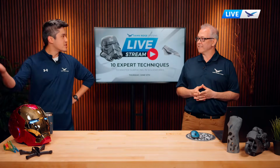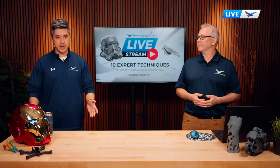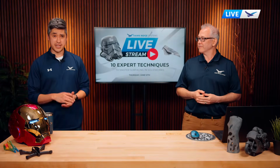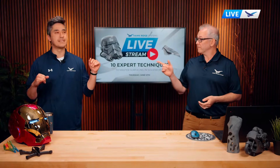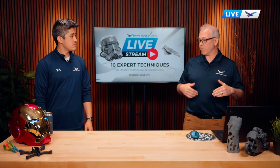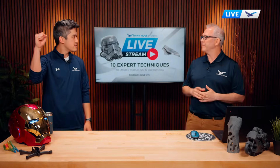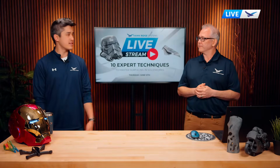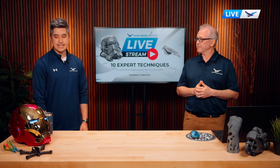I was saying, how many features are in this model? How would we even go about checking that? Performance evaluation on the Evaluate tab. It'll tell you how many solid bodies are in there, how many surface bodies, how many features, graphics triangles now. And when you adjust your part, like if you suppress a feature, it will change that. Or even rollback. Yeah, it'll update. But yeah, it's got the graphics triangles now as of 2025, I think.